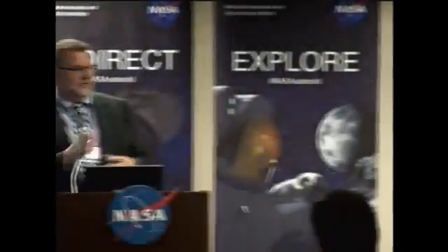Sure. We actually talked about that again in the analysis of alternatives. That's one of the ideas that came up: putting a gimbal of some sort between the bag mechanism and the spacecraft. And that works great for single-axis rotation, but as soon as you get the second and tertiary axes going, your spacecraft is going around and you run out of gimbal range. You just can't do it on the second and third axes. And Brian's dynamic animation, if you saw that, is a great demonstrator for that.